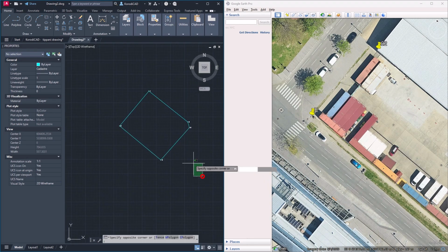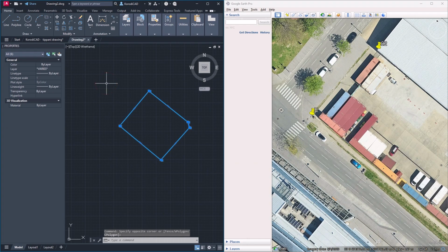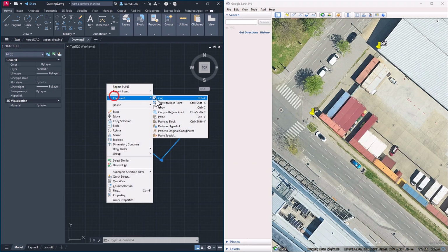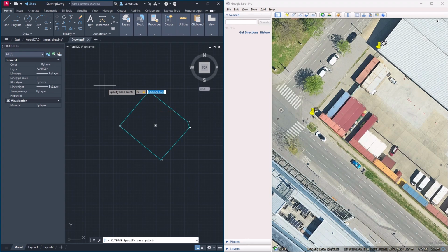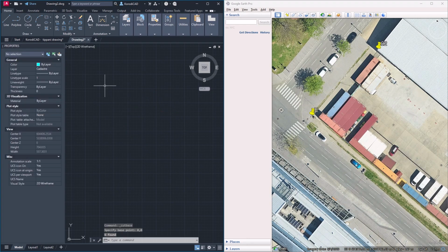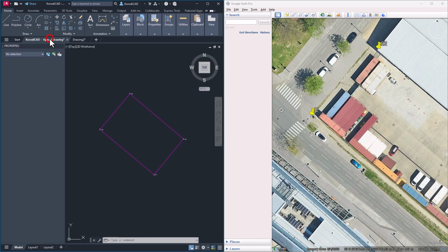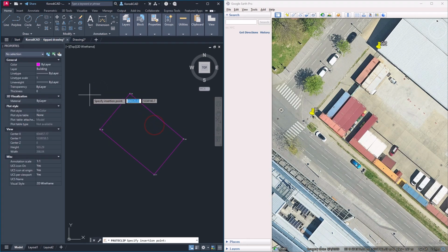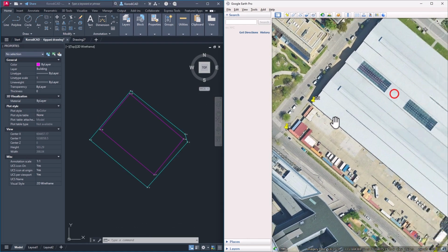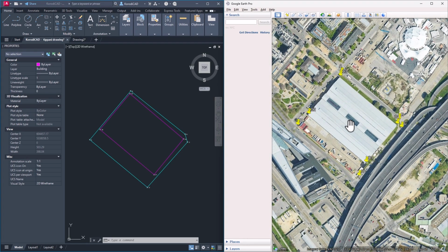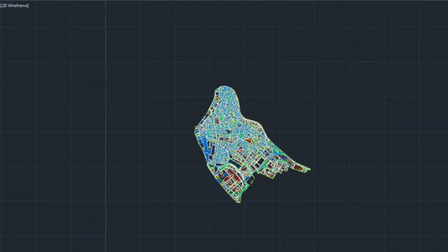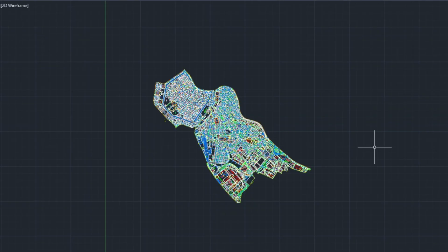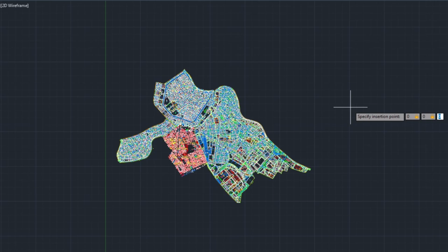Once the cadastral boundary has been drawn, copy or cut it out with the 0,0 point and paste it into your original drawing with the 0,0 point. It can be seen that, knowing the reference point, the drawings can be matched with the precision defined in the units. So that entire cities, countries, practically the entire map of the Earth can be merged or broken down into parts.